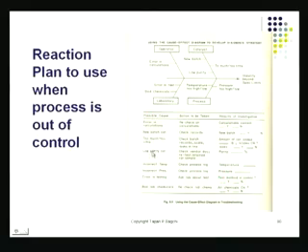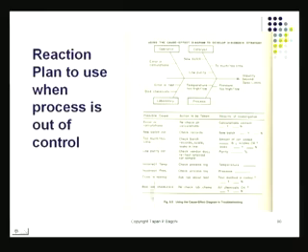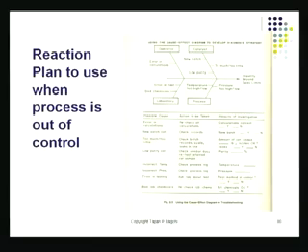So you go over these things: low purity catalyst, that also could be a reason for this, incorrect temperature, incorrect pressure, error in testing, or bad lab chemicals. So you're actually getting a bad test coming out of the laboratory. This is our checklist. Whenever we've got an exceptional situation, pull out this checklist and start very systematically going over these items, 1, 2, 3, 4, and just see the results of your investigation.